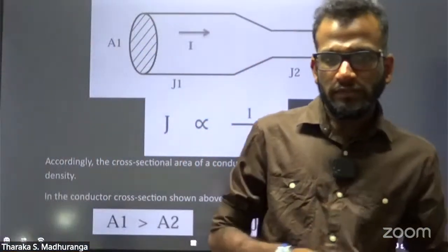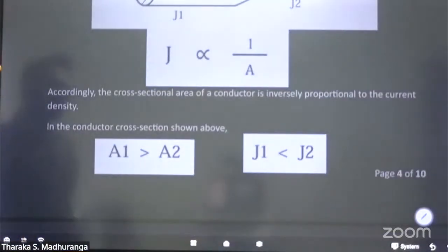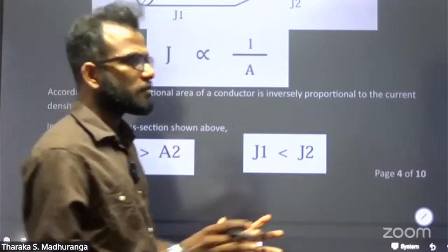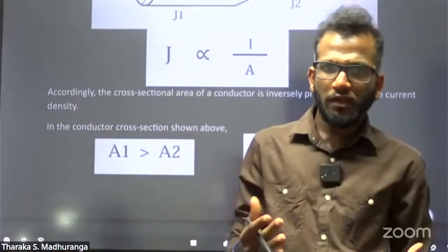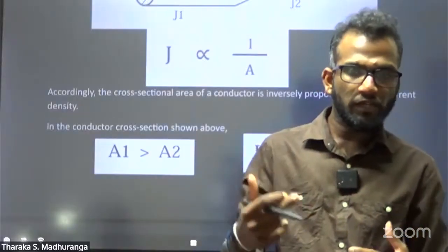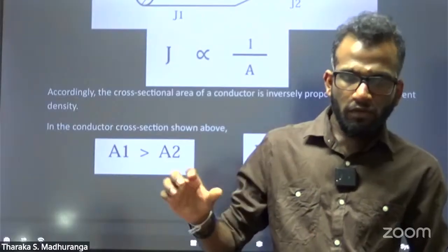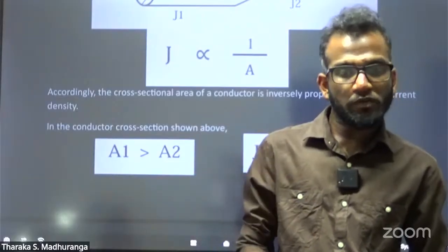Okay, that's very important. When we select conductors for whatever purpose, according to the amount of current flowing, we have to select suitable conductors with proper cross section area.